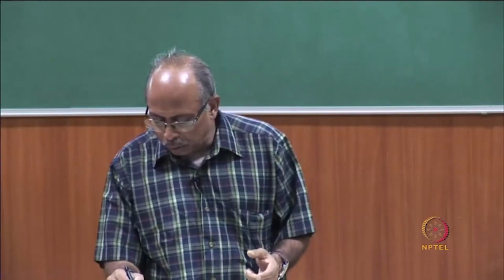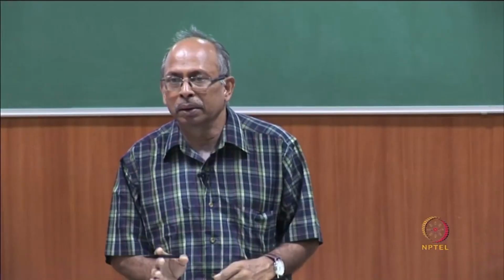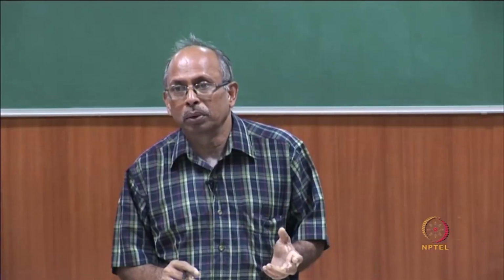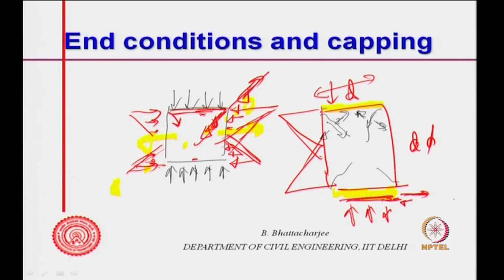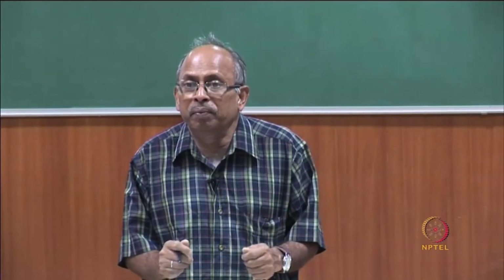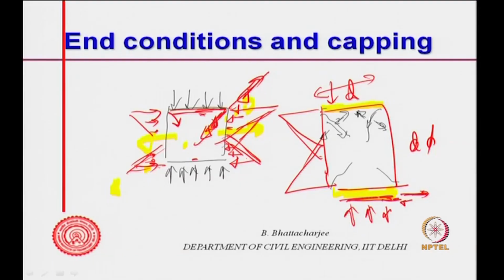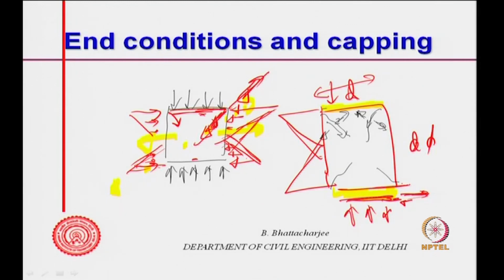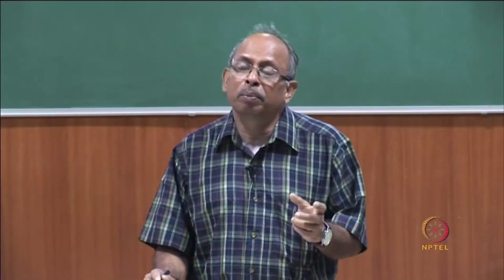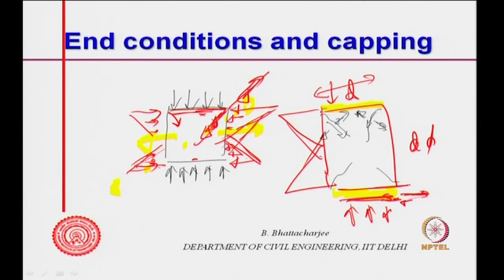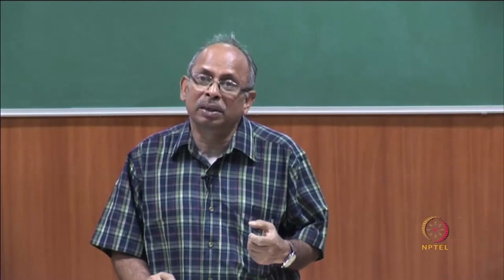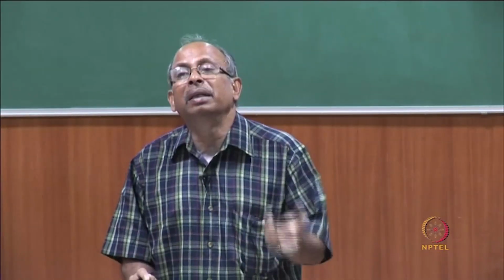So, it is Poisson's ratio which causes it to deform along the transverse direction, and its stiffness is an important issue. If it moves quite a bit compared to the stiffness, the resistance to movement, for a given force, then for two different cappings, the more it moves, the more it will cause the concrete to move along this direction. If it is stiff, then this directional strain itself will be low, therefore Poisson's effect will be minimal. So, the higher the Poisson's ratio of the capping material and the lower its modulus of elasticity, the more it will tend to nullify the Platen effect.